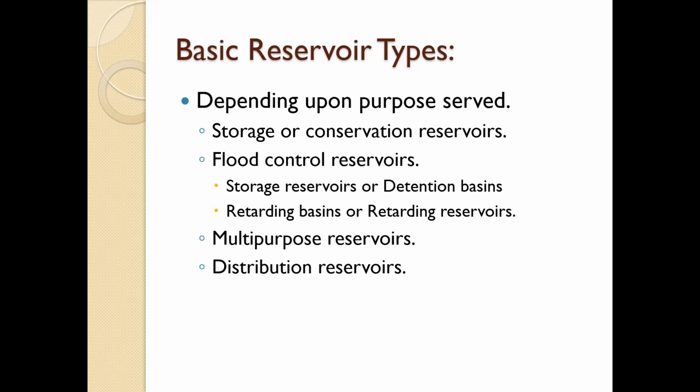Now the flood control reservoirs. The flood control reservoir is generally called a flood mitigation reservoir. It stores a portion of flood flows in such a way as to minimize the flood peaks at areas to be protected downstream. To accomplish this, the entire inflow entering the reservoir is discharged till the outflow reaches the safe capacity of the channel downstream. The inflow in excess of this rate is stored in the reservoir, which is then gradually released so as to recover the storage capacity for the next flood.